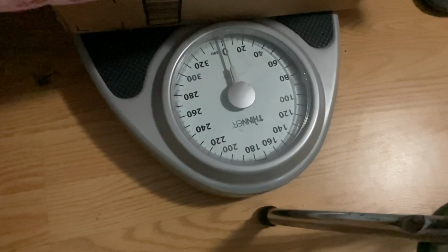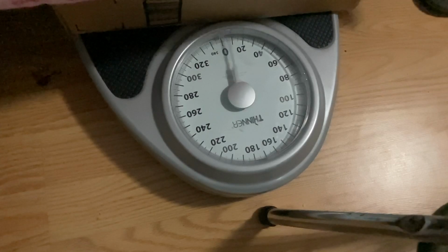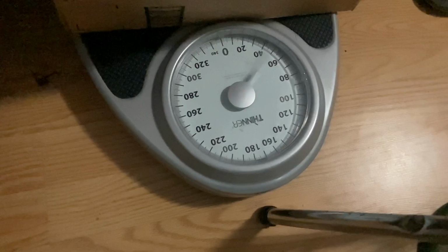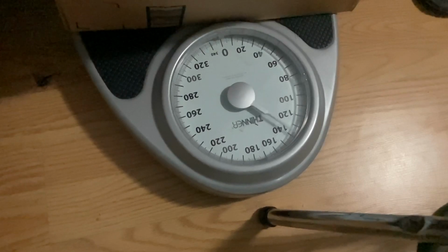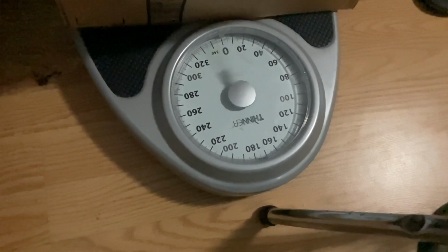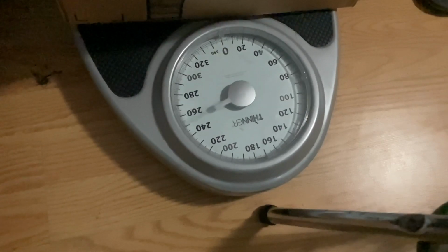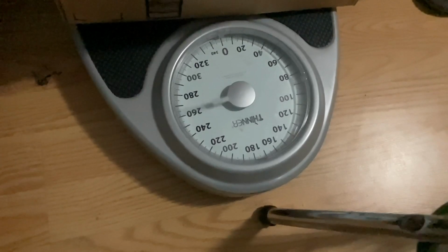In this next recording, we have a pillow inside the box. And so the pillow is going to extend the time of impact and hopefully generate a smaller force. So more time, less force. So again, we see the load jump up as it falls. And you can see it's increasing a lot more slowly, and it peaks out at about 140 before it drops back off. And we'll also notice that it doesn't oscillate nearly as much because it basically comes to a stop in the one hit.